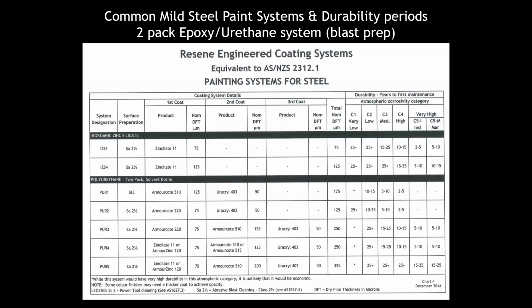Now this is a guide. This is the coating systems within the guide, and just giving you a simple example here of one of the most common systems that we'll give you, and it's in the polyurethane top coat area. So the PUR systems. Just as a note here as well, in our conditions in New Zealand, we're typically wanting to put polyurethane type top coats on our exterior steel, and that's because it provides excellent UV protection. Epoxy type systems generally in exterior exposures will have early onset of chalking on the surface, so we're really always looking to put a polyurethane coating on as a top coat.